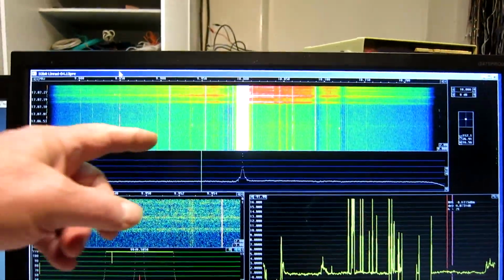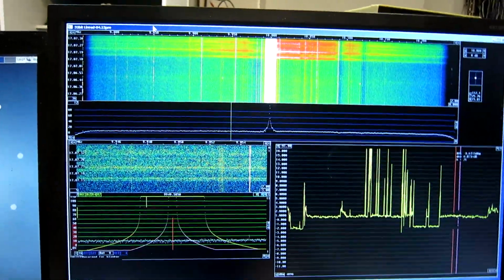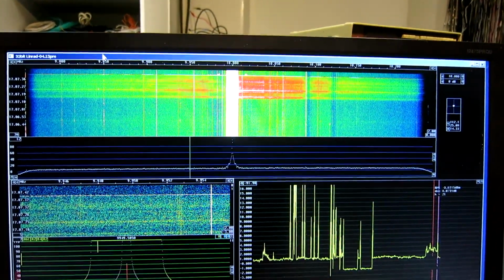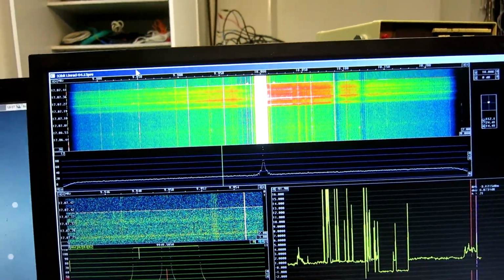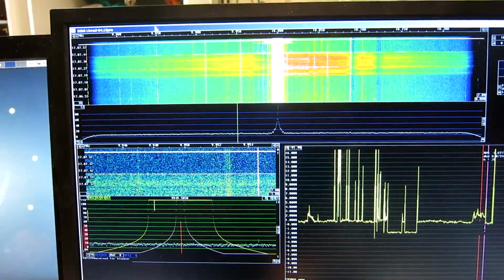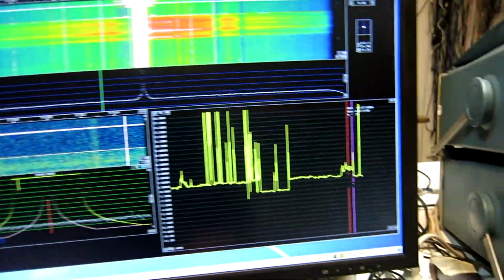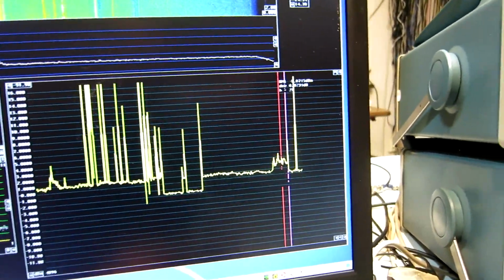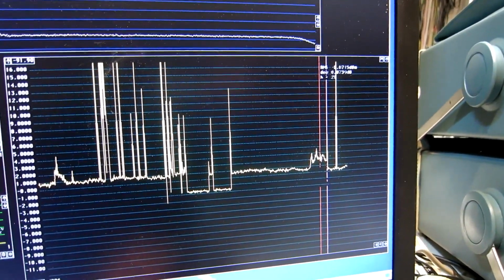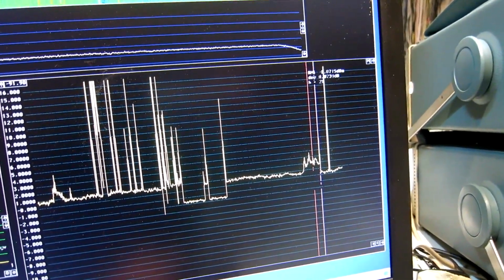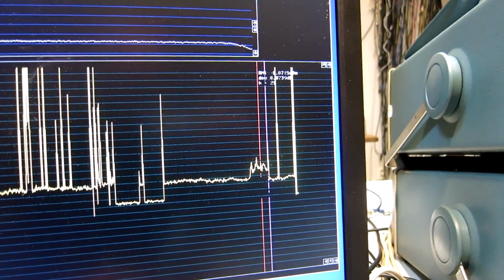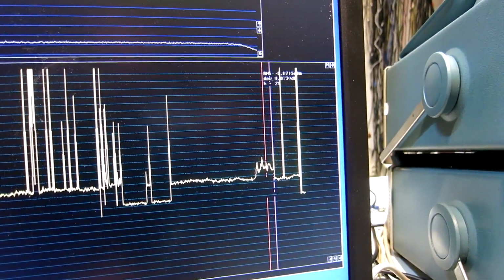And you can see clearly here I introduced some instability. I don't know why, but I tried to knock at the oscillator and that fixed it for now. So I have to look for whatever problems could be there. The bad connectors, for example. Well, this is the level that should be there when things are stable. And I switch off the signal by making the stepped attenuator very large. And I bring the signal back.